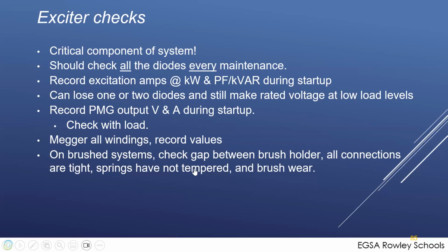Another thing, it's very handy to have startup values again. During startup, I run it to full rated kW. I measure the amps and the volts of each phase. I measure the excitation current everywhere I can, and the excitation voltage, and make sure it's all there. So I have that information going forward.